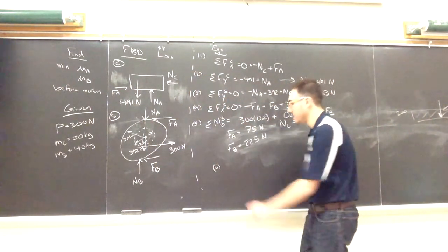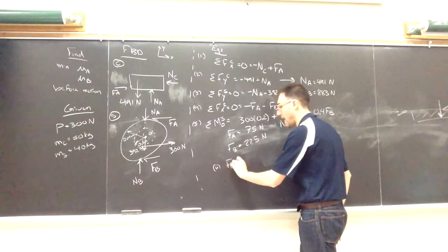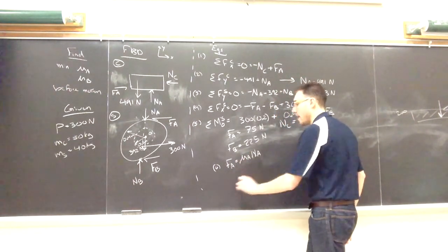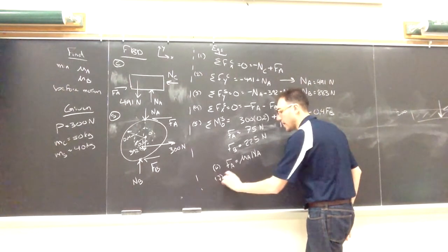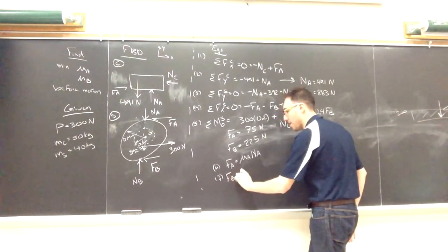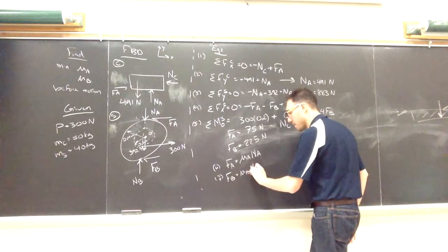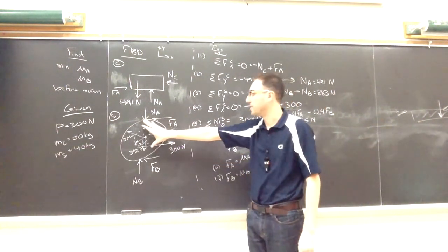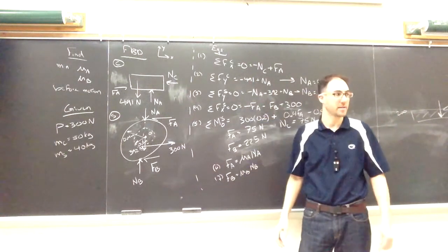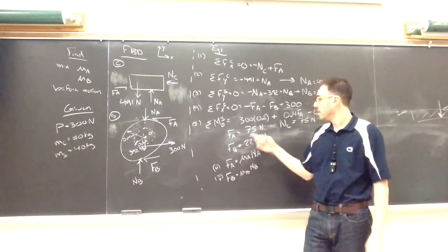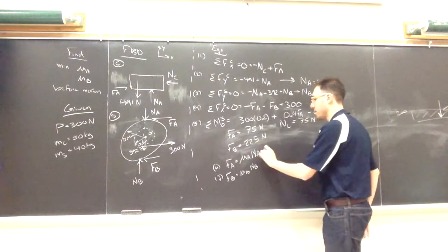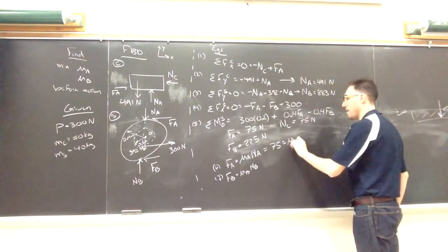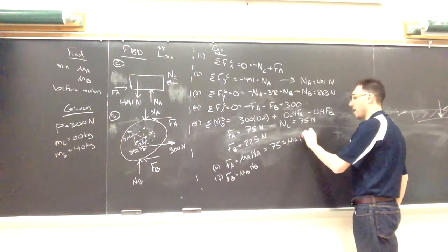Now I can add those additions, that the friction force at A is at its maximum value, and the friction force at B is at its maximum value as well, simultaneously. Because they would both have to be at their maximum simultaneously for the spool to be able to slide to the right. I know FA is 75. Mu A I don't know, but NA I know is 491.